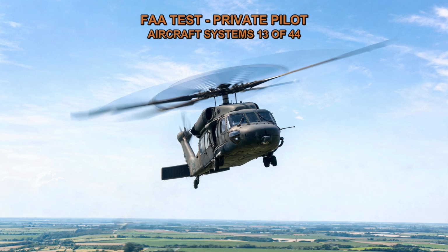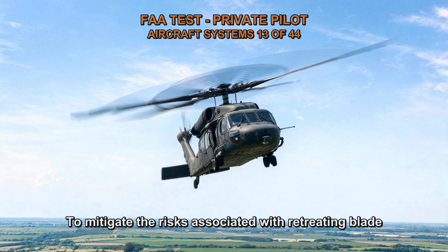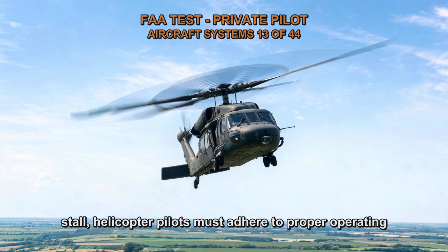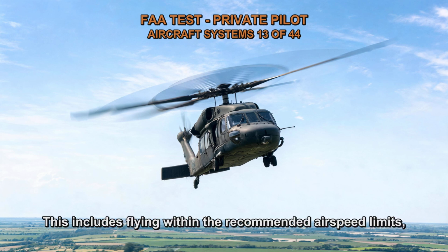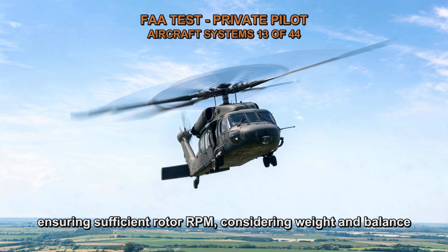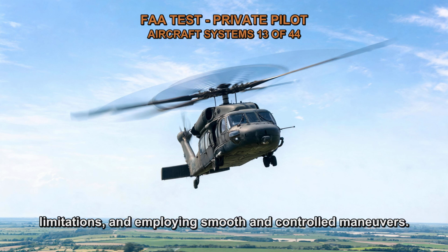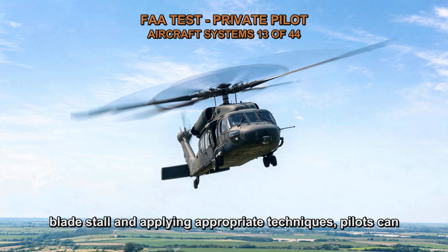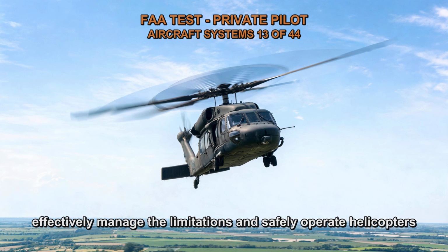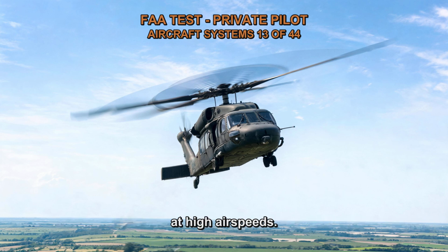To mitigate the risks associated with retreating blade stall, helicopter pilots must adhere to proper operating procedures and limitations. This includes flying within the recommended airspeed limits, ensuring sufficient rotor RPM, considering weight and balance limitations, and employing smooth and controlled maneuvers. By understanding the factors that contribute to retreating blade stall and applying appropriate techniques, pilots can effectively manage the limitations and safely operate helicopters at high airspeeds.